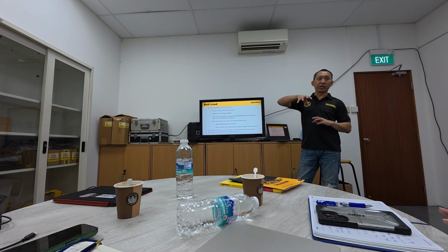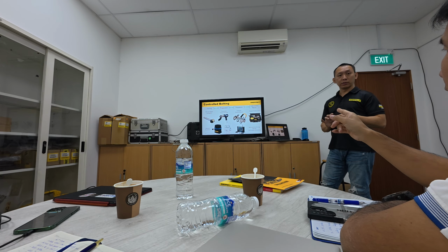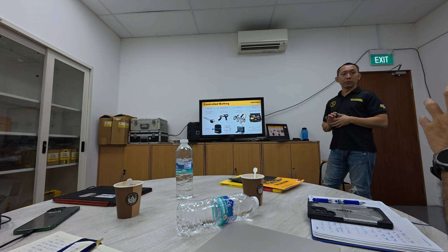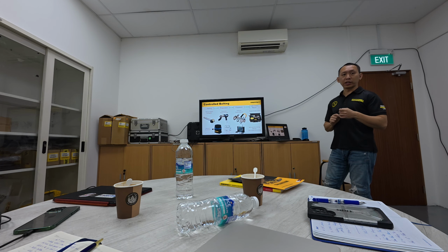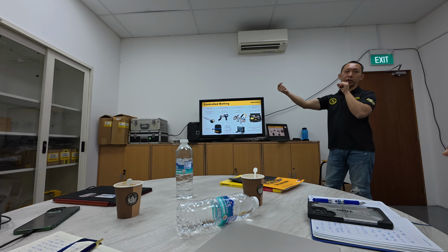And of course we have more advanced tools using ultrasound, like a bolt monitoring system. This uses ultrasound, like an A scan or B scan, and based on the result we can estimate how much force is in the joint. These are things like the Boltscope Pro and Ultra from Hydratight. It uses ultrasound, with a scope and the sound feedback.